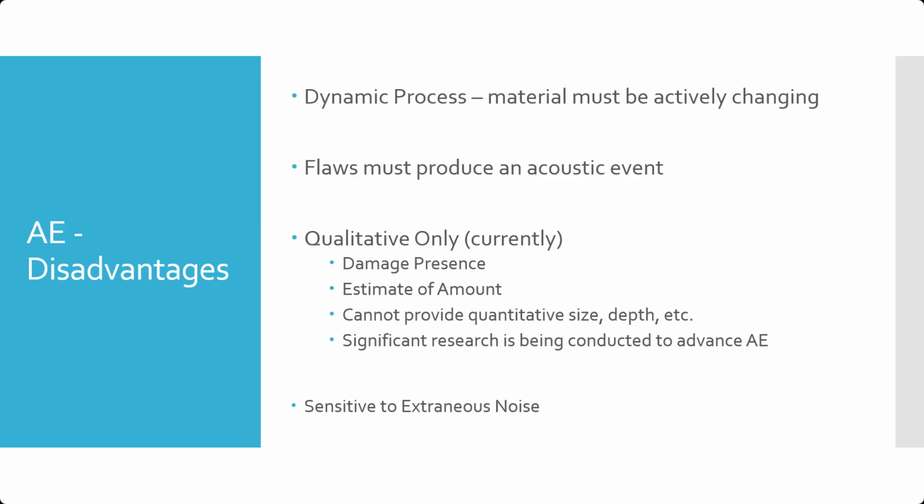That rotation is not going to produce anything in the tens or hundreds of kilohertz or megahertz range. Most of the vibration is going to be in the 3,000 hertz range. But there are cases where that could be a problem. If you do have extraneous noise, you have to be aware of that and not have it give a false positive, a false indication, or you might need to filter out certain ranges.